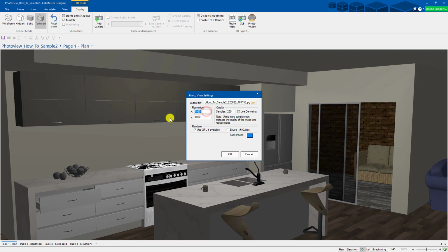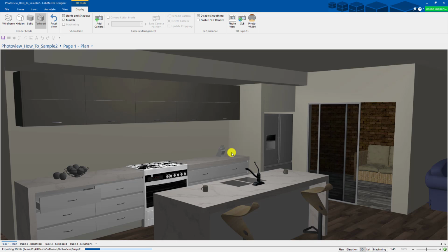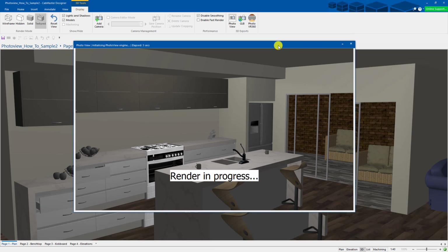Again, drop it back to, I don't know, 1200, 700, 40. Just get your view, what you're looking at. Again, you can go front on the entire kitchen if you really want. You don't need to see out the window, but you get a different angle of what you want. Then you do a high quality render. Again, minute and a half. That's all it's really going to take. So it's quick and easy to go, yep, change it around, do a quick one here for, you know, your 18 seconds.